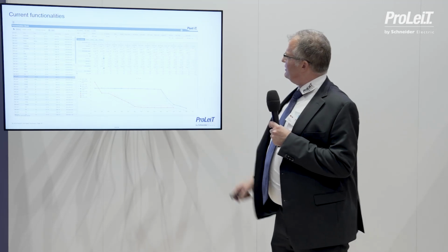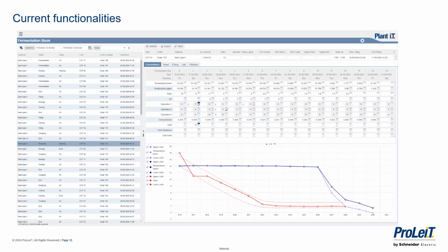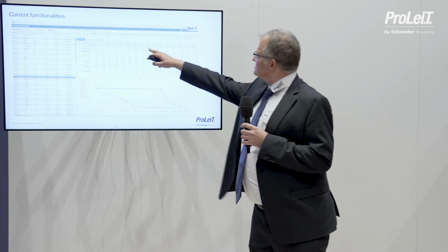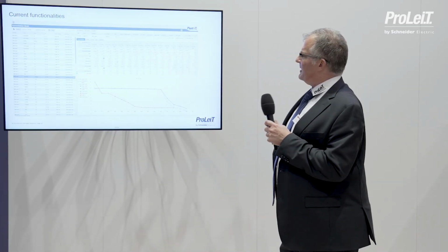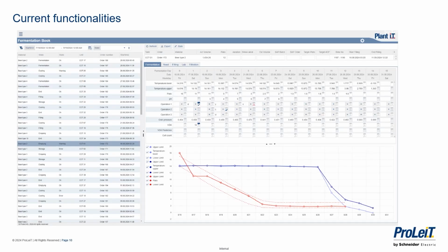It was filled 4 times, with brew numbers 1187 up to 1190, and we also see the total volume of beer currently stored in this fermenter. And in this overview we can make the parameterization, meaning the lower limits and upper limits of the different values I want to have shown in my fermentation book.